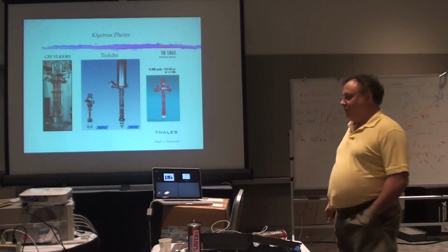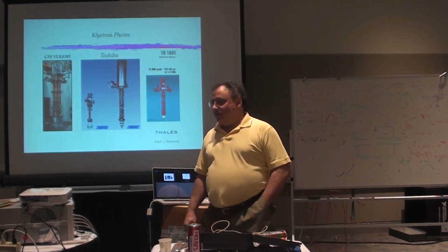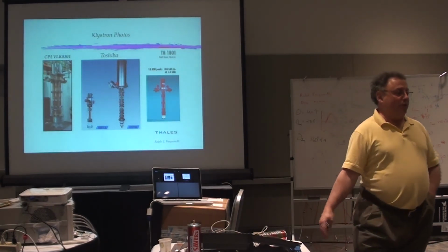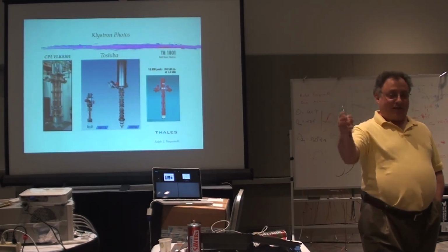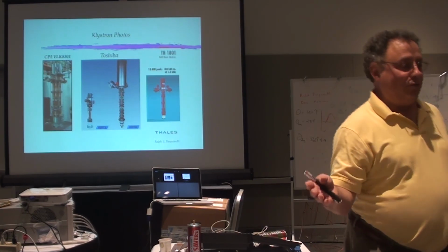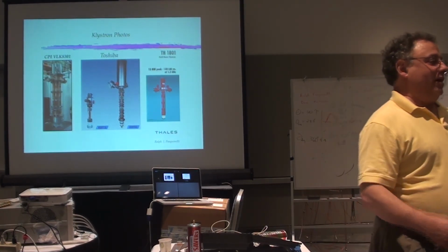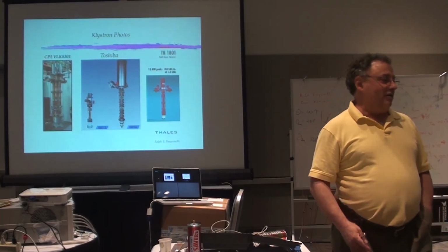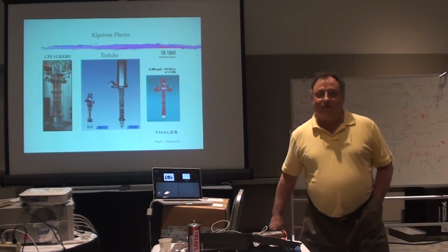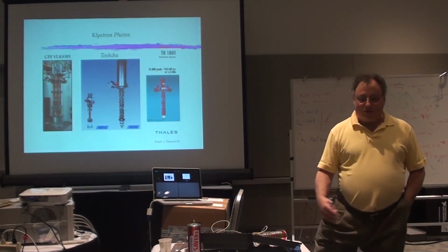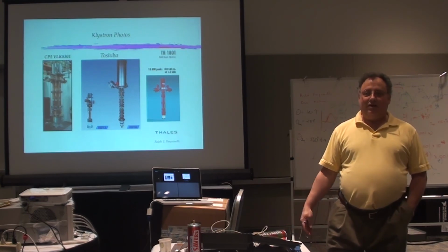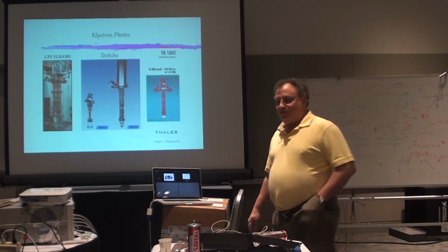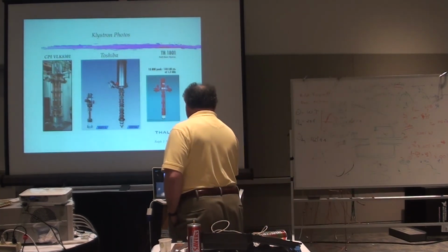And that became the reason why it's 1.3 gigahertz, because there was a power source that existed from a previous user. And that's almost always the case. I mean, that's what's going on at ESS. They're at 352 and 704 megahertz because CERN pioneered those frequencies, and therefore they wanted to stick with something that someone had already done. Of course, they still need to develop lots of different kinds of power sources, but many of the frequencies exist because someone had already done the NRE cost to develop the RF power source. And so that's where you see a lot of these frequencies routinely show up.